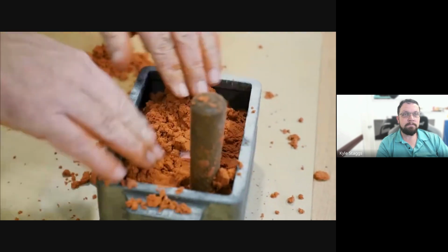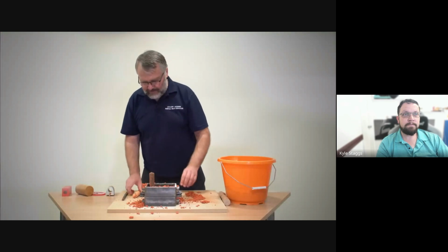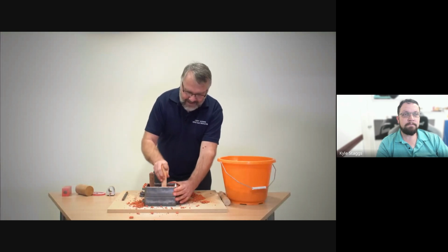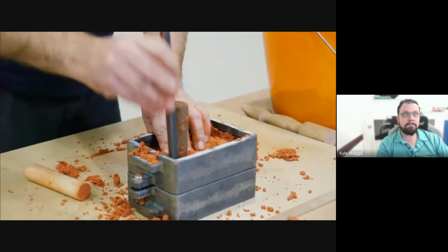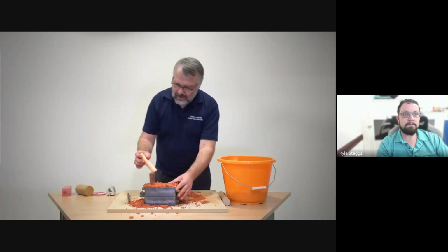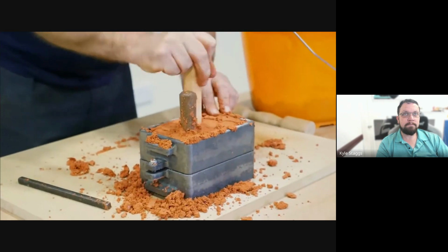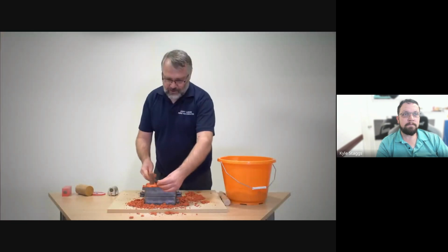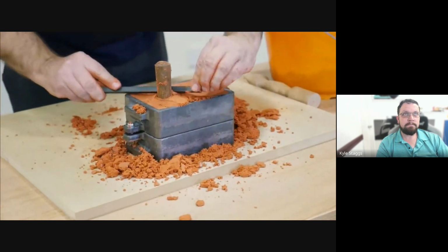We repeat the process. Mary Berry would be proud of me doing this. Pressing the sand down and using the ramming tool again to firm the sand. The ramming tool doesn't fit down into the corner, but that doesn't matter. You can use any old thing. I'm using the strickling bar. The sand on the second box, the cope, doesn't need to be quite so firmly rammed as in the drag. We use the strickling bar to strickle off the top the best we can.